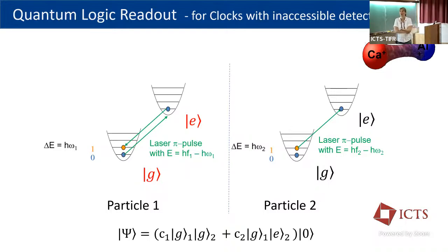That's why many quantum computers are actually moving now back to the microwave regime, because it's so difficult in the optical to get a pure local oscillator that doesn't have the tiniest noise here in the sidebands. It's not completely decided. There are big companies and billion-dollar raises that are driving optical qubits, but more and more people are also now trying the microwave qubits for the better spectral purity.